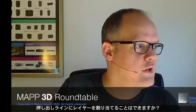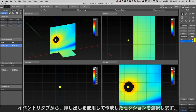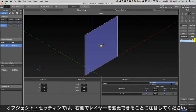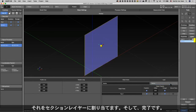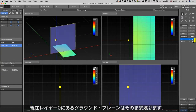Can we assign a layer to that extrude line? Yes, we can. Okay, I'm going to add another layer, and let's call that layer section, and that will contain the section view that I just made. So I'm going to select from my inventory tab the section that I just made using extrusion. Now I go to object settings, and in object settings, notice that on the right side, I can change the layer. Currently it lives in layer 0, but now I'm going to assign it to the section layer, and you're done. If I now were to hide that layer, then my section plane disappears altogether, whereas the ground plane, which is currently living in layer 0, stays in place.